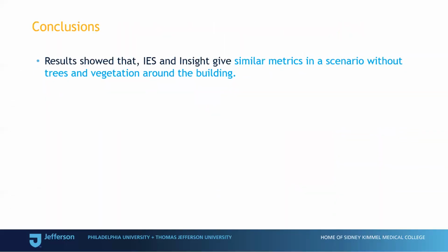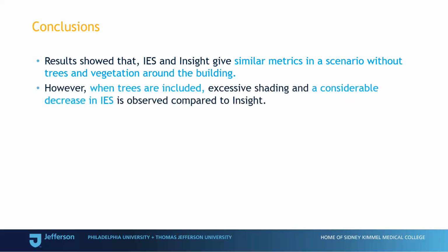The study investigates how changes in interior, such as shading and furniture, and in exterior, such as vegetation and trees, would affect the amount of daylight observed by the building occupants in a campus building, by using two software applications: IES from Radiance and Insight from Autodesk. With similar parameters set, they ended up validating one another's results, except in the case of results with trees. Metric results showed a significant correlation between the lux values of IES and Insight.